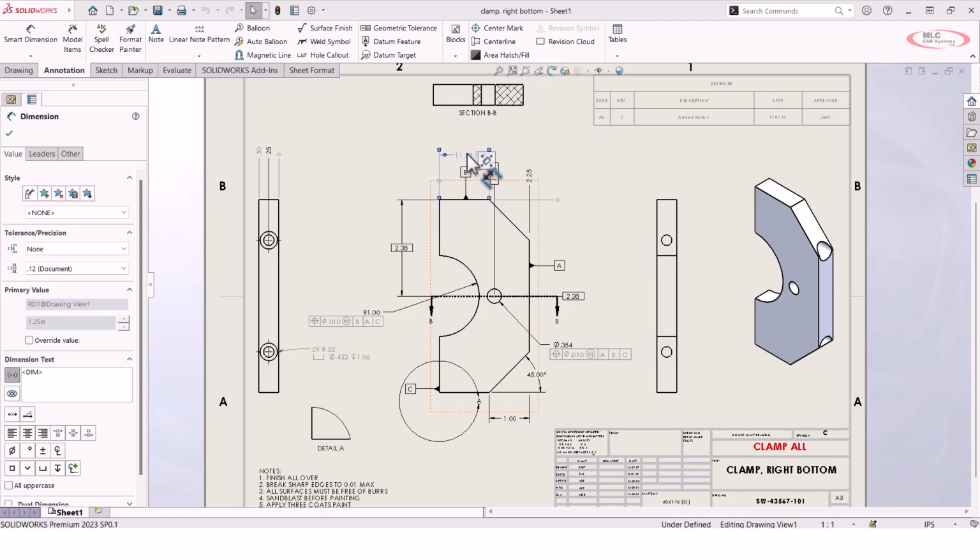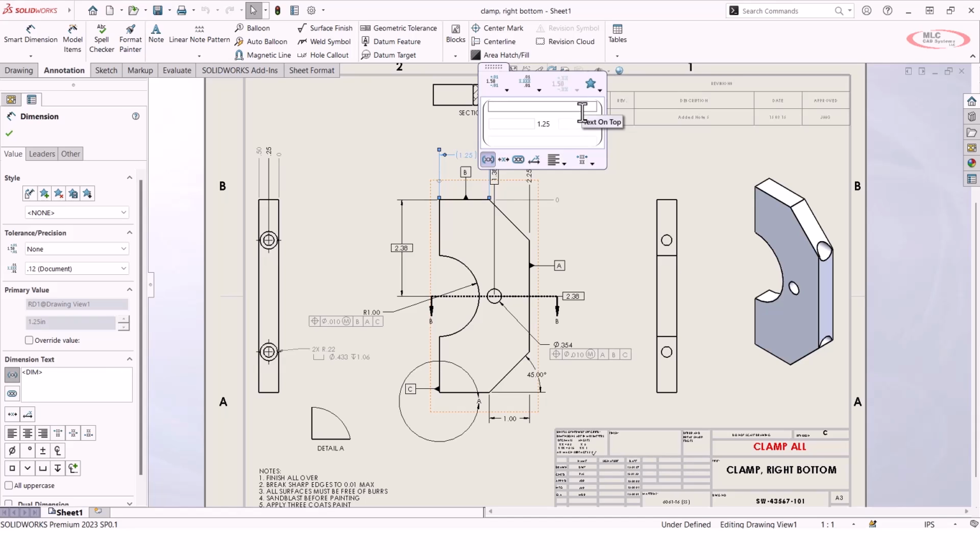This is another thing I didn't list on my initial list of features that are often overlooked. But this guy right here, if you move towards it, is called the dimension palette. And it is something that is very easy to overlook. But it offers all the functionality you have in that property manager on the left, but it's right there in the middle of your screen, so you don't have to navigate away from the graphics area. I also like how it's formatted because it's very clean. It's neatly organized. It's compact. You've got text boxes for putting in things like typical values or just custom notes to your dimension. But on the top row, you've also got the option here to add your tolerance.